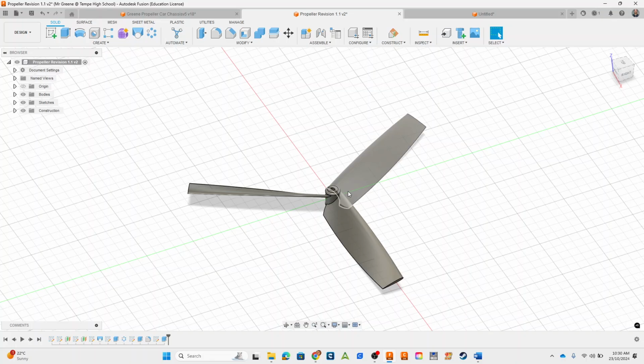Okay? By how much, we don't really know, but we understand that concept. Okay? So what I can reasonably assume, if this is moving slow and this is moving fast, it's going to be interacting with the air differently. So all I'm making here is a hypothesis that because this is moving really fast at the outside, it's going to be creating more drag if I'm not angling my propeller to move the air efficiently. What that angle should be, what that optimum angle should be, I'm not sure. That could be a subject for your experimentation.